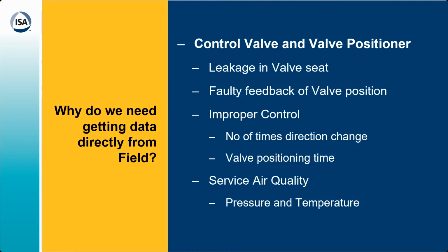A control valve is a very costly asset, and it comes with the valve positioner. So it gives you the leakage in the valve, faulty feedback, and improper control of the control system. Suppose then you can see the number of times valve direction changes and what your valve positioning time is, so that you can tune your PID loops.